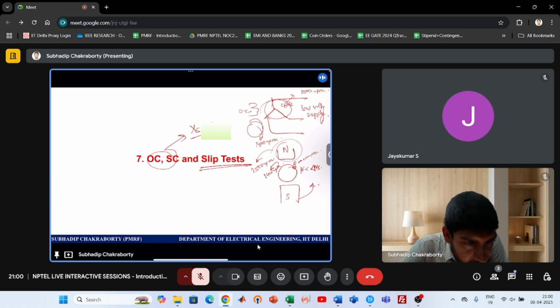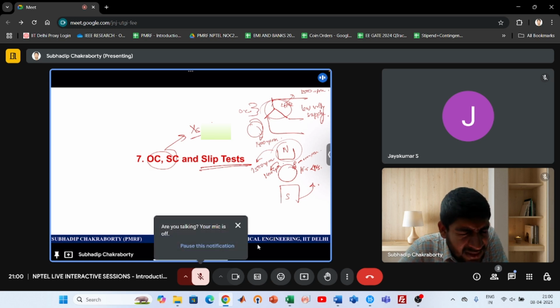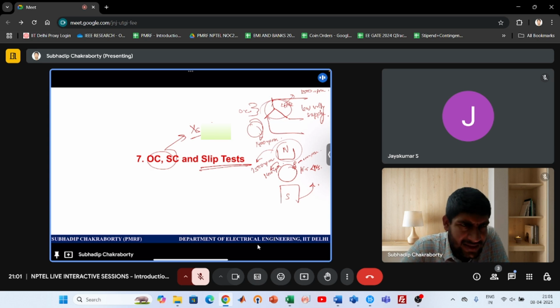That is agreed, right? Voltage should be induced in the field coils, because till now the rotor and the RMF were synchronized. That's why no AC voltages were induced in the rotor. But now AC voltages will be induced in the field coils. What I was telling all this time was DC; for normal operation, it is DC. But now in this test, I open circuited the field coil, and still, since there is a relative velocity of the RMF with respect to the field coil, some slip voltages, AC voltages, are induced. This much is agreed, right?